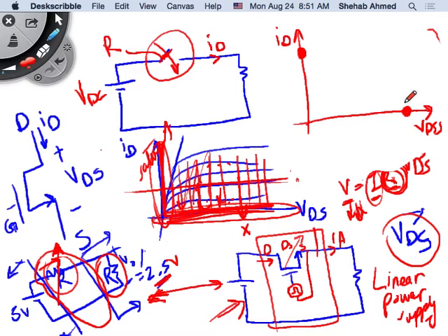But for example, if you're designing a power supply, like we used to do for operating in an oil and gas environment that is operating at 150 degrees Celsius, the leakage characteristics of devices are very different at 150 or 200 degrees Celsius. There's a lot of leakage. And we're always operating the devices out of their area of comfort. It's like taking this class outside in the desert. This is not your area of comfort. We will not be happy. The devices are not happy in a downhole application. It's very hot outside. They don't like it.